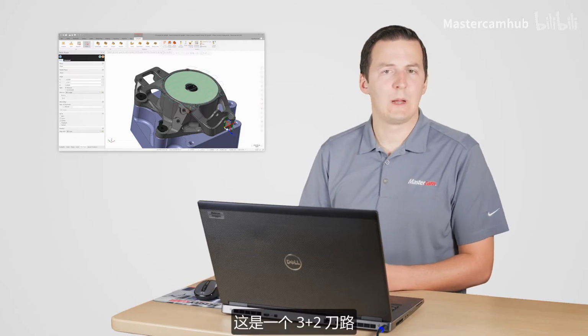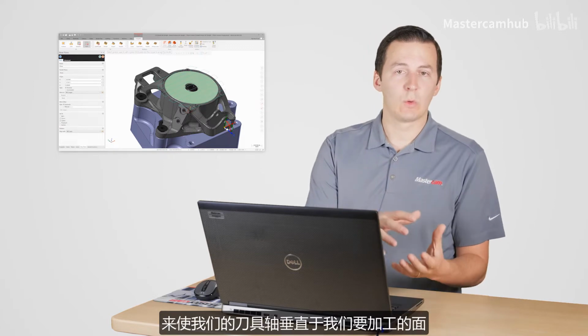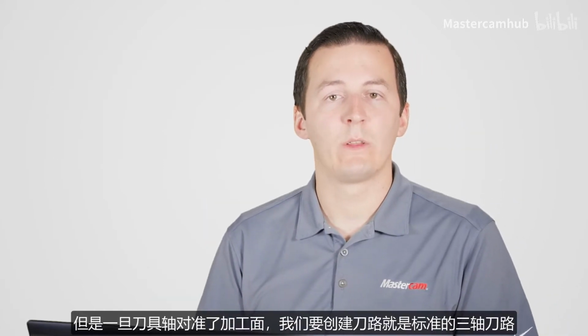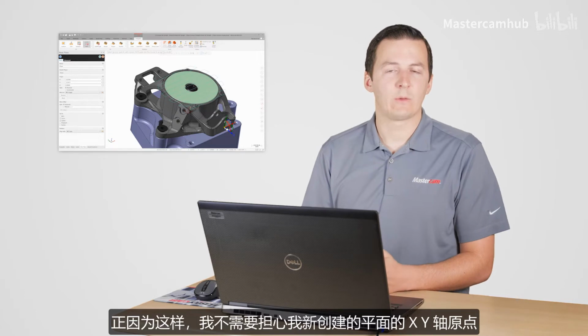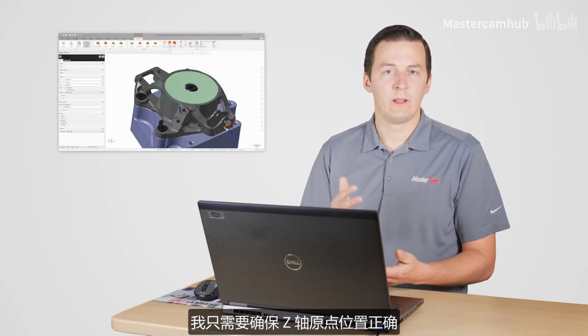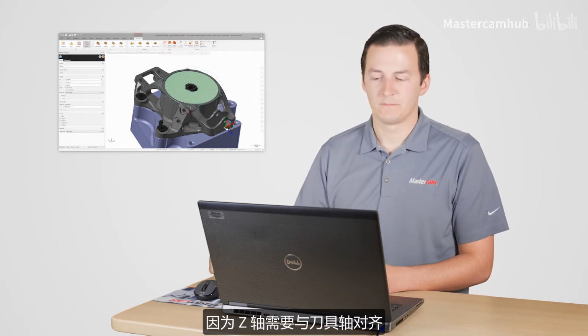This is a 3+2 operation. What that means is we're using the multi-axis capabilities of the machine to get our tool axis normal to the surface we want to machine, but the toolpath we're going to cut once the tool is aligned is a standard 3-axis toolpath. Because of that, I don't need to worry about the XY origin of my new plane. I just want to make sure that the Z-axis origin is aligned properly, since that is what will align the axis of my tool.